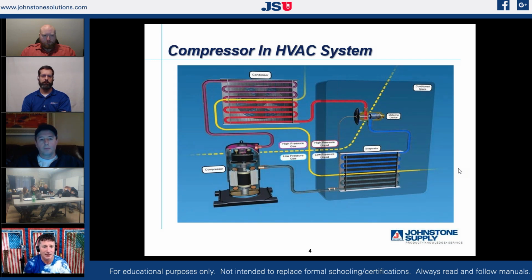That's what we typically encounter. What if it was a commercial ice machine? If it was a commercial ice machine, I may not be moving air across my condenser. I could have a tube and shell heat exchanger with city water passing through that, and I'm removing the heat from my tap water and just sending it back down the drain. It's the same principle, right? I'm just moving heat across my condenser.